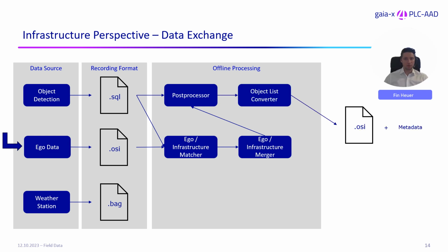After we post-process the data, we convert this data, this object list, into the Open Simulation Interface file format, also with some meta information which describes the data recorded. Additionally, we export this information as ASAM Open Scenario, which is a file format to describe scenarios which can be directly fed into simulators in order to replicate the scenario. Therefore, we also generate some metadata.